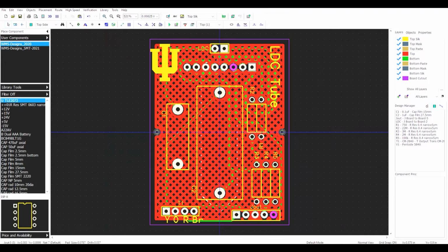And then for the output connector, you usually put pins, you know, this is pin 1, so you could write 1, 2, 3, 4, 5 there if you wanted to. Anything you can do to make it less likely that you or whoever is building is going to mess up is always useful, always helpful. And then in all my adjusting of things, one of my ID numbers moved. So I'll put that back up here. Oh, because I moved that resistor, remember.